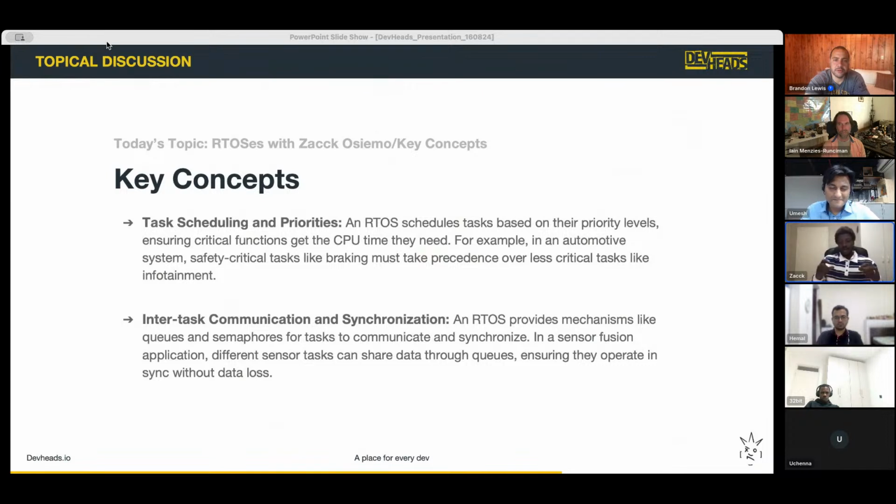When you're doing this, you would probably schedule a whole firing sequence or a whole timing sequence in order to make sure that it happens in the order that you want. That arrangement of things to happen in which order is the scheduling that you need. This is where you'll need an RTOS, which gives you features for scheduling as you need. Things can happen in a certain order, and they always happen in that order. So it's deterministic. You always know what will happen. You can expect that it will happen the way you arranged it.